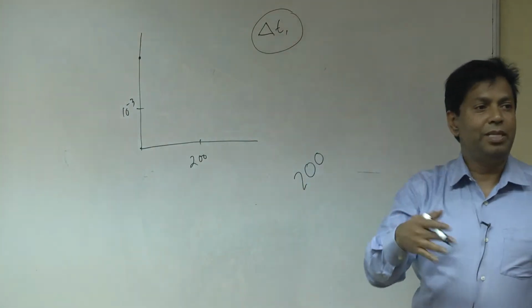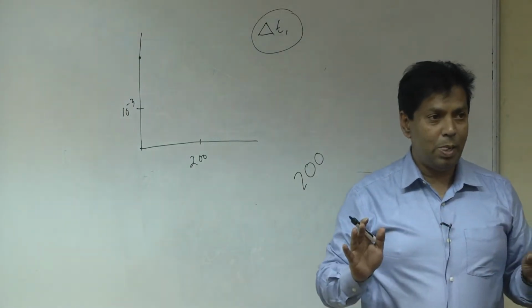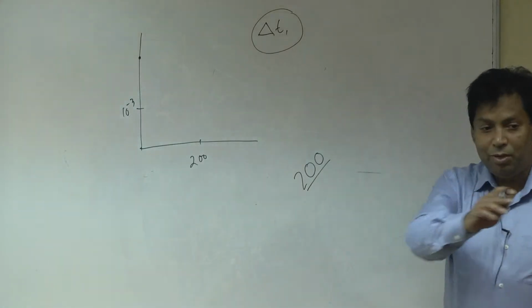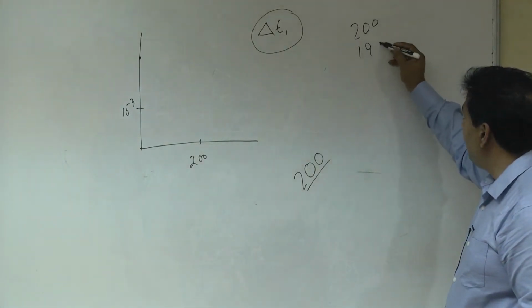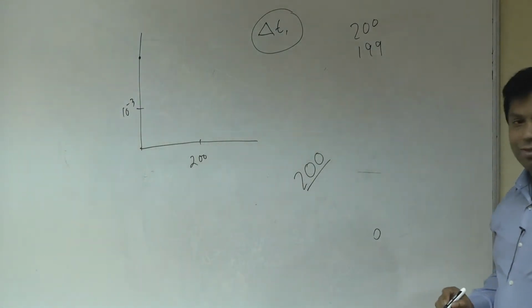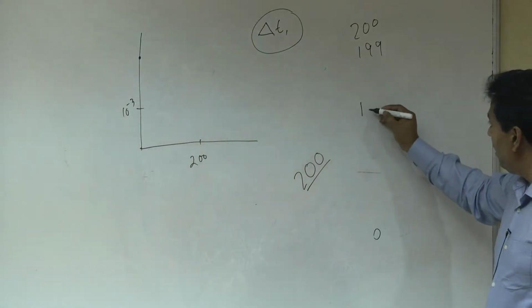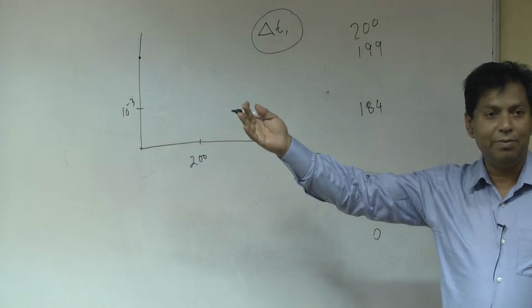Sometimes people are confused. They think the solution is converged, but it is not converged. So you have to check. When the simulation starts, it starts with 200, 199, okay? It's coming down. So be careful, it is not going up to 0. Mostly I saw this computer converging at about 184 or 183, okay, then going to the next time step.